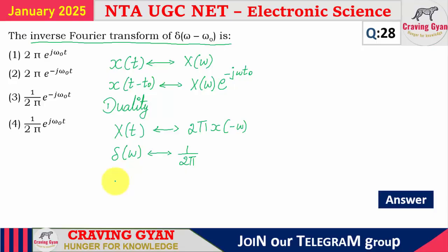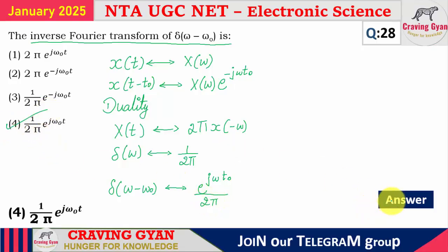So for this, if I'm applying the shifting property, that is delta of omega minus omega naught, nothing but a frequency shifting. If I am applying the same thing, I am going to get, that is exponential in the other domain, that is e power j times of omega into t naught divided by 2 pi. The corresponding option that is going to follow is option 4 is correct. For the 28th question, answer is option 4.